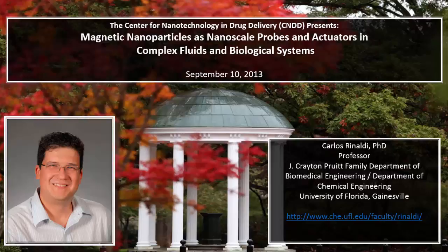What we think is going on here is that it's a probe size dependence. When you're at high temperatures, the gelatin is not associated to each other. It's free in solution. The particles can freely rotate, and the macroscopic viscosity is low. At a certain point, you start forming the initial parts of the gel matrix, but there's still enough space between the particles. So your rheometer starts to pick up these structures, and that can span the gap of the rheometer.